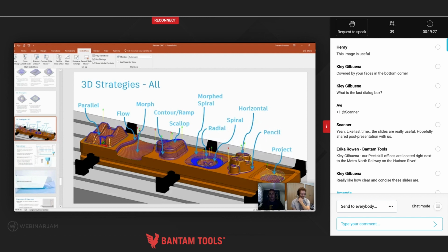Here you can see Fusion in 2D and 3D has got a really wide range of methods for manufacturing and using certain toolpaths. And the one thing to call out about 3D toolpaths too, right, is that they're model aware, whereas 2D toolpaths are not necessarily model aware and require the user to select the geometry that you want to utilize that toolpath for. Whereas like 3D adaptive clear, you could basically turn it on and you can press OK and let it go. Yeah, that's one of the nice things about Fusion. So yeah, absolutely, great point.